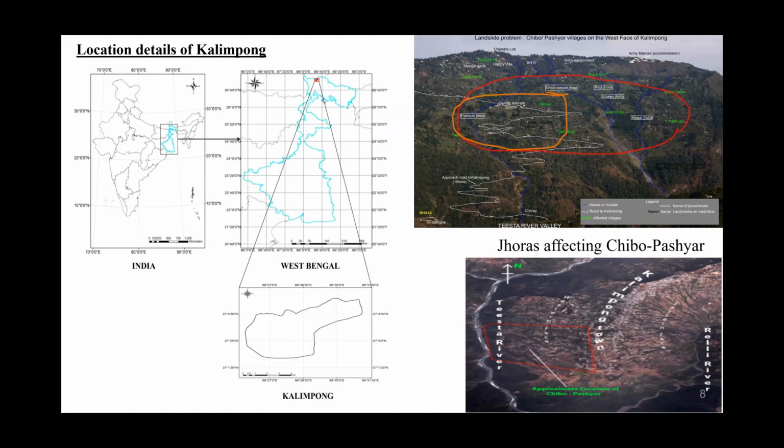Because of the huge increase in the built up area, whatever streamlets are in that region are gaining energy and flowing on either side of the slope. These blue lines, which they locally call joras, are natural streamlets, and they are joining each other because no water can percolate inside the top part. And during the flow down, you can see the erosion along the slope, right?